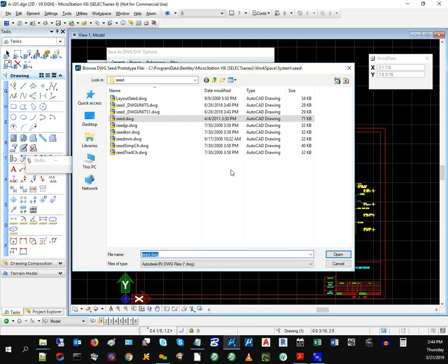And again, depending on the units that you want to have, this is a similar thing that you want to care for in going the opposite way. In other words, instead of DWG to MicroStation, going out, just make sure you use a seed file for the DWG side that has the appropriate levels or layers and fonts and things like that you want the output file to have once you save out to a DWG form.